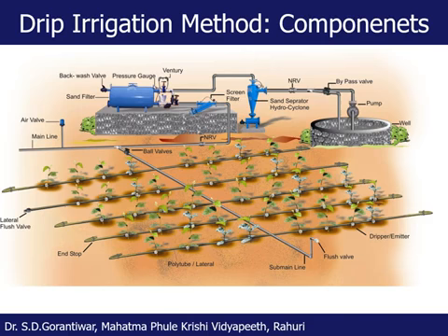In fact, it is considered that the efficiency of a drip irrigation system has to be 90 or 95%. So in order to avoid that, we have to keep the pressure difference between the first dripper and the last dripper such that we get 90 to 95% emission uniformity. This will be covered in your design class.